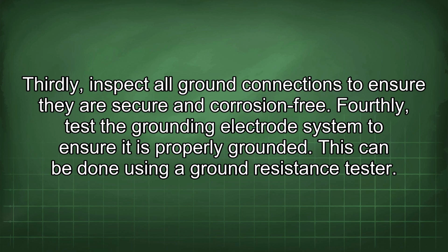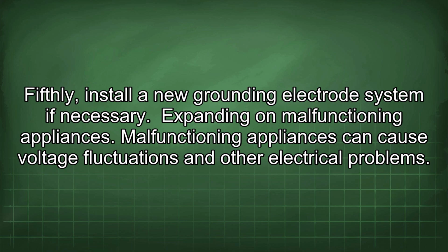Fourthly, test the grounding electrode system to ensure it is properly grounded. This can be done using a ground resistance tester. Fifthly, install a new grounding electrode system if necessary.